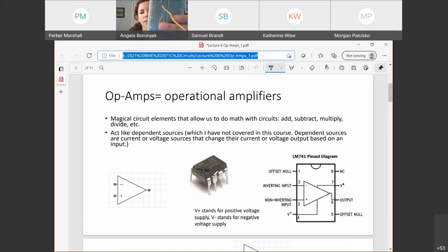And we'll see that we put them across this gap so that the pins on one side can get a different voltage than the pins on the other side. Remember, your breadboard connects a group of 5 pins horizontally, if it's not the power rails, together, but not across the gap. These 5 pins can be a different voltage than the same row across here. Okay, so that's what they look like in real life.